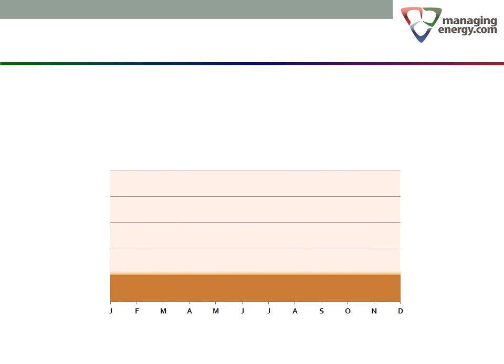In building up a model, the first part we'll look at is the base load. Base load energy use is consistent throughout the year. For any given period, the consumption is tied to the length of that period. By convention, we will use number of days as the unit of time, so the formula for base load consumption would be number of days times the daily consumption. Mathematically, we show this as Q equals TX, where Q is the consumption for the period, T is the daily consumption, and X is the number of days.